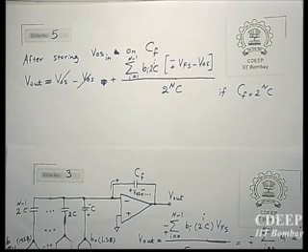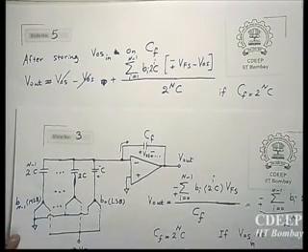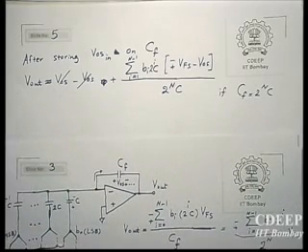However, if this offset changes, then you need to compensate every cycle, which is very impractical because you need to have one offset compensation phase every conversion cycle, which will slow down the operating frequency. And the whole motivation behind using a parallel conversion will get affected. But if you can approximate this offset to be almost constant, then you can do it once and then all the time it will operate properly.